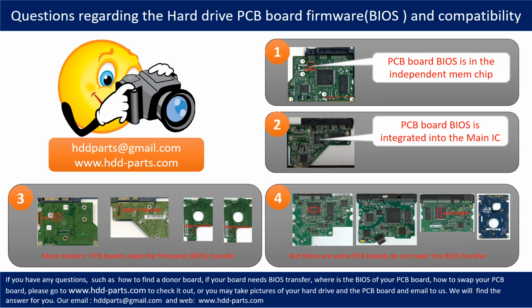Most of the modern hard drive PCB boards need the BIOS transfer before swapping the PCB board, even if the donor boards are identical with the original boards in hardware. We have to transfer the BIOS from the original board to the donor board. Then the donor board can work on the original hard drive.